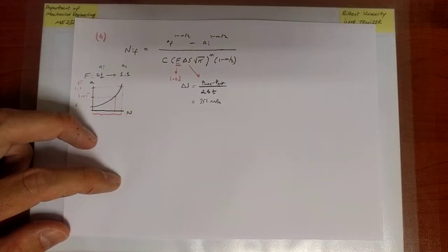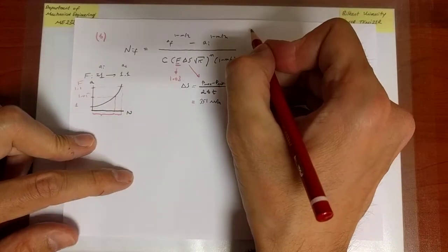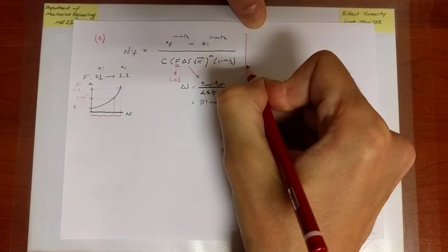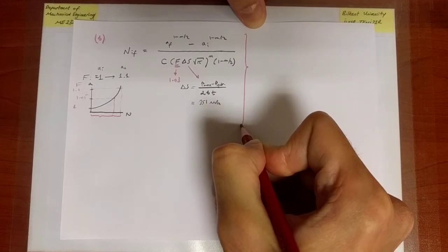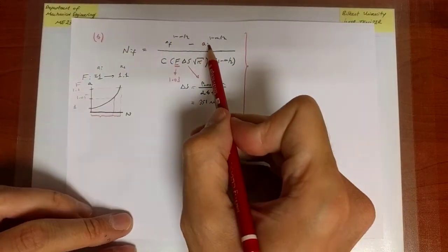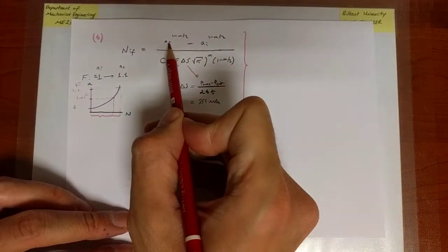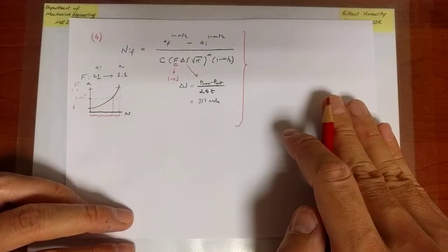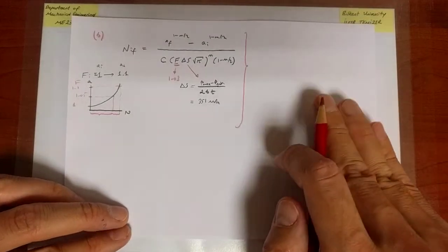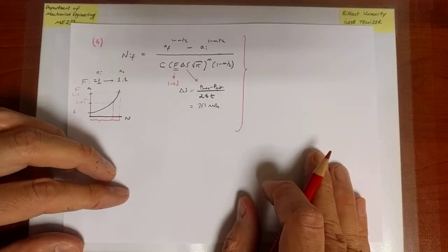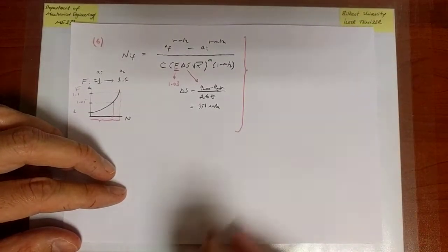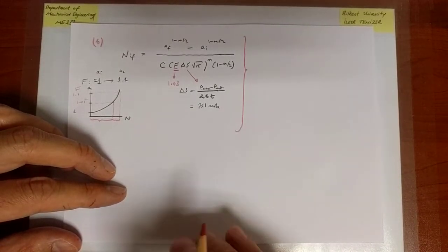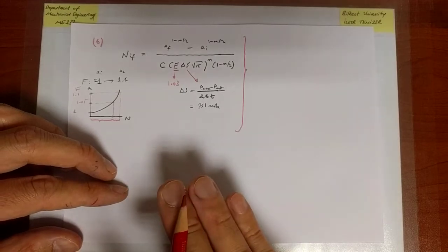So the next thing that we need is the material data. Now remember, we are looking at a scenario where the crack grows from the initial size to a final size, which has to do with fracture. So we're going into the high-end regime towards the fracture, where we know that the rate of the growth of the crack rapidly increases. It's not in the log-log plot scale linear anymore, like Paris suggests. So we should really be using Foreman.